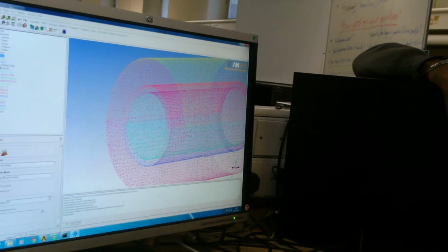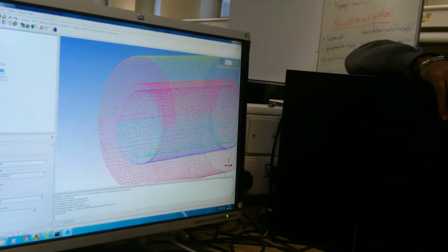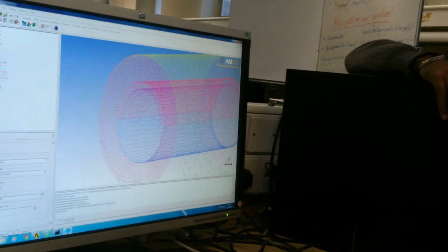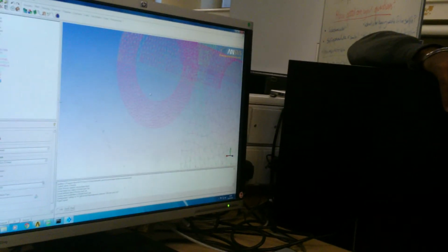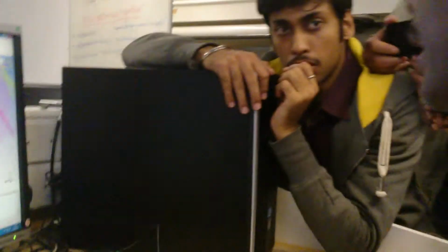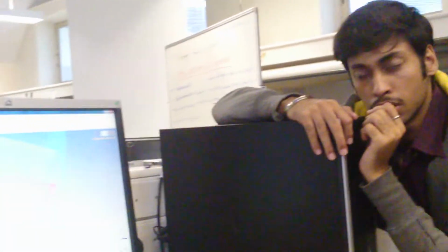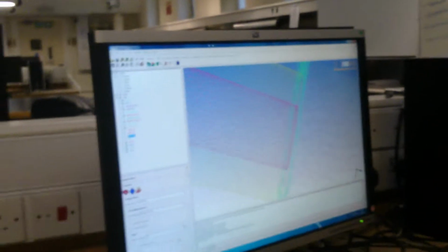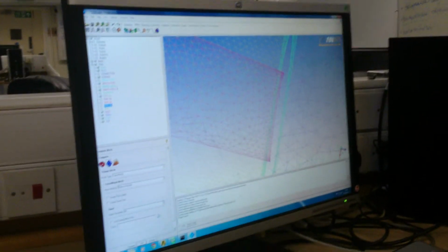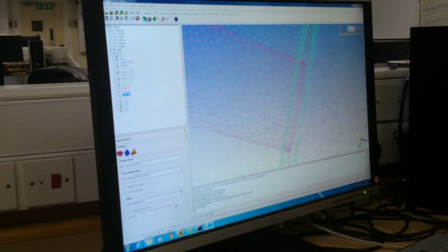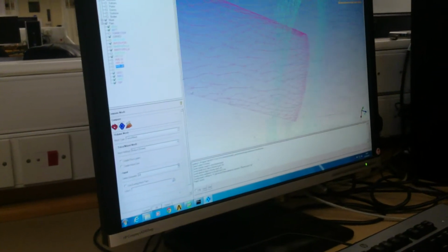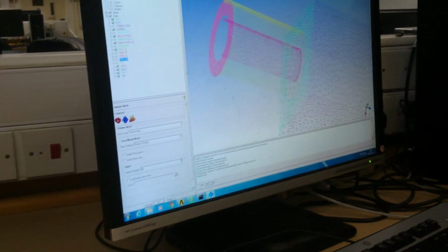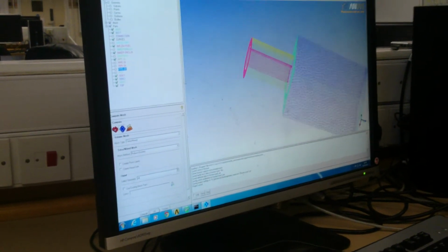Coarse mesh can give you some sort of solution, but not really. It's like you're even allowing the impurities to enter also. So we will see. That's why I encourage you to use two kinds of meshes to compare between them. Fine mesh, the 1.1 ratio, you can see here, it is very small, and then it starts expanding, increasing by 1.1. So this is the mesh.